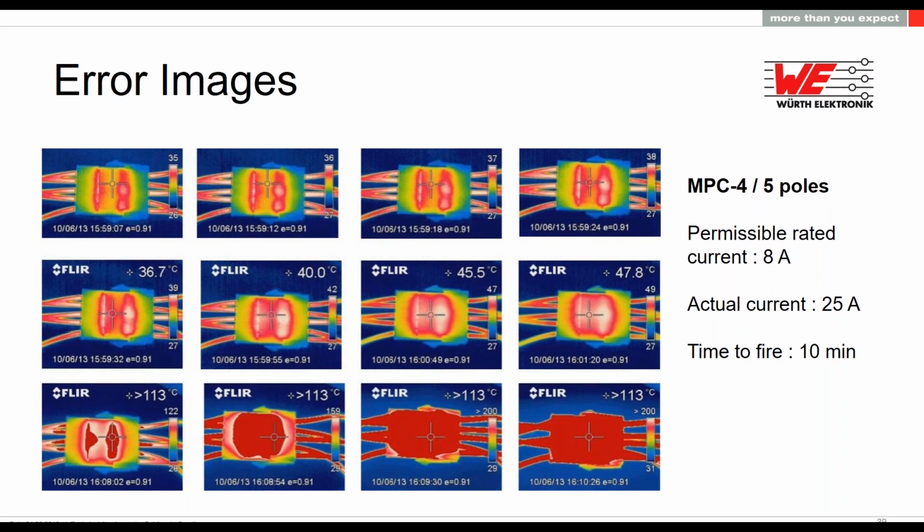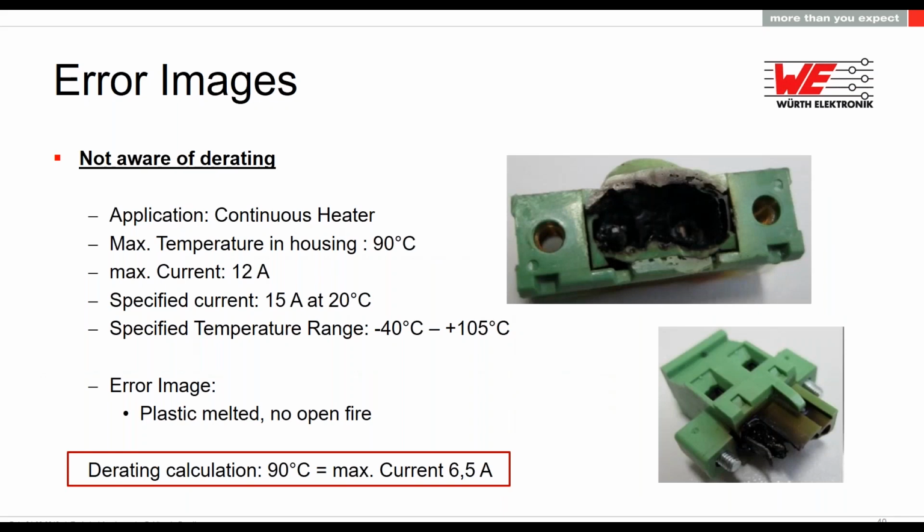So if you drive connectors to the limit, really take care and also explain this in the measurement of the derating, that you plan enough time to let the system run when you measure it, when you try to evaluate if it's stable, because this loop is getting faster and faster, and if you just measure in the beginning, you can probably not see what will happen in 5-6 minutes. This can happen if you're not aware of the derating.